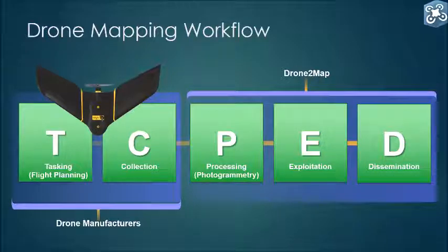Your flight planning is generally done using a software that comes with your drone. You set your capture area, that's your area of interest. The number of passes, meaning how much overlap there will be, affects your accuracy as well and quality of imagery. You'll get coordinate information as well as some other details, which I'll mention more about to you in a few. After planning is your drone launch and actual capture of your imagery. So you plan, you launch, you capture, and you now have imagery. And this covers the drone portion of your workflow.